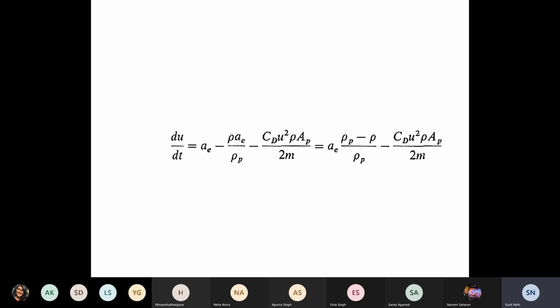So you can say that whatever we do not know about the fluid flow, whatever is unknown about the hydrodynamics, we have put all of those into this fudge factor, or into this CD variable. But the good thing is that this CD is evaluatable. So I won't call it a fudge factor. In essence, it is an experimentally determined variable.